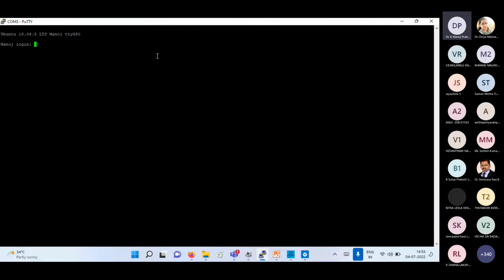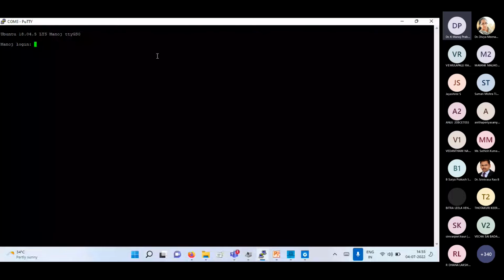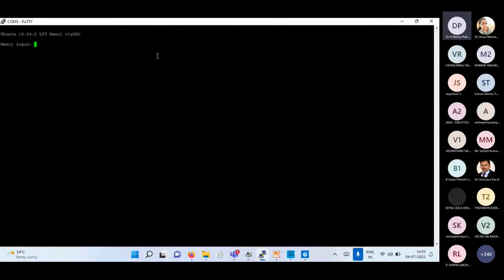So I'm going to connect. First of all, for the Jetson Nano, I take the JetPack software and dump it to the board using the SD card. Now the kernel will be activated and do the analysis in the Jetson Nano. Before that, I'm going to connect it to Windows. Here there are two modes: one is the head mode and the other is the headless mode. Head mode is where we can directly connect it to the computer.